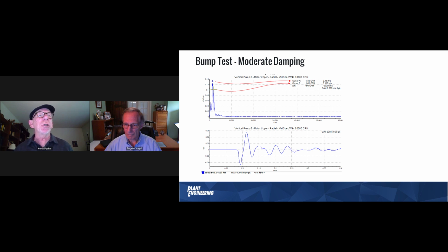Quicker question. Is it typical to have a machine failure that prompts this analysis? Kind of yes and no. A machine failure, if the machine is still running, you could do an operating deflection shape on it. If you have severe vibration and you want to know why it's vibrating, yes, you could do the operating deflection shape, but the machine has to be running. If the machine has failed, meaning that it no longer runs, you can't do the operating deflection shape.